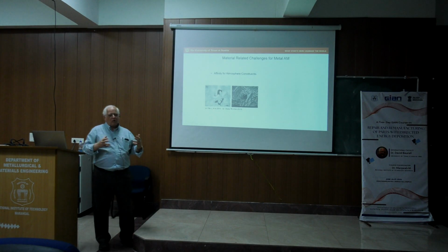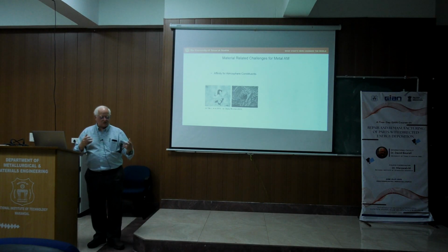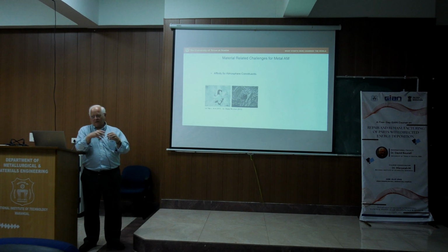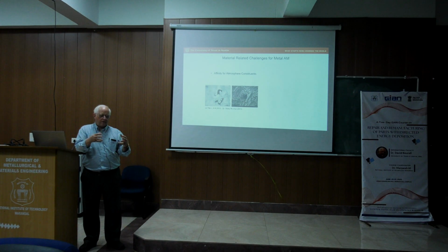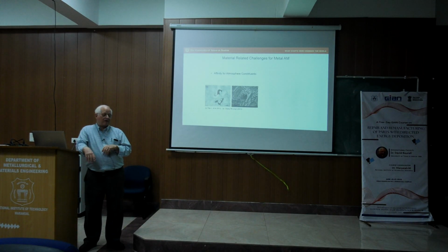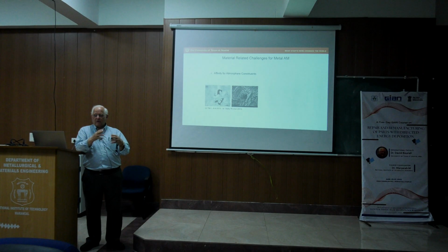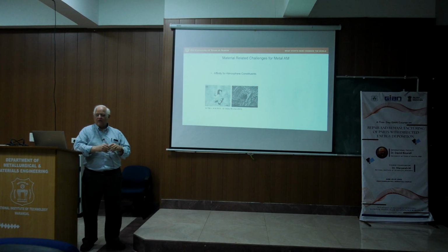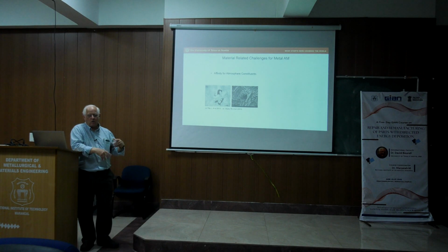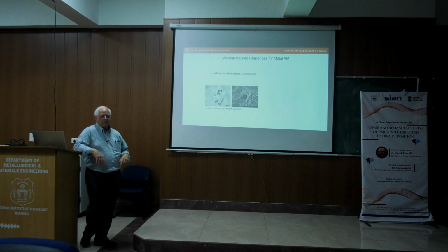And generally it's the same story: the feedstock itself has alloying elements or foreign matter in a distributed position. But when we melt and re-solidify during additive manufacturing, there's a redistribution of those elements or contaminants, and we can pick them up in a more macroscopic, measurable way.